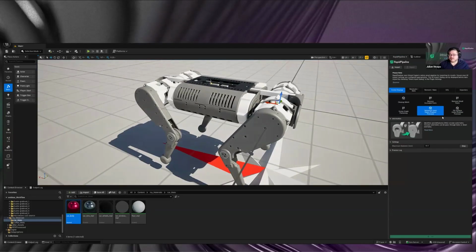For now, I will mainly demo the defeaturing here because that's a more interesting algorithm, and it actually works on topological holes or boreholes, through holes which are basically supposed to be there and you will always get them. The fill surface holes is more like, okay, if there's actually a one-sided surface and it has a circular hole, that's not really that common. So usually that's broken topology. Maybe in very rare cases, it's actually on purpose, and then it would just fill up these circular holes on a one-sided plane, for example.